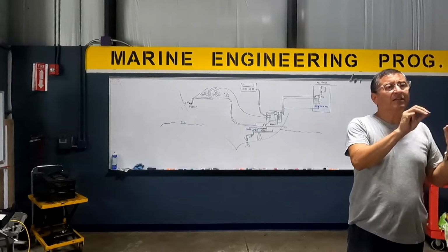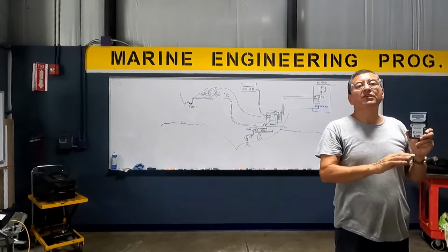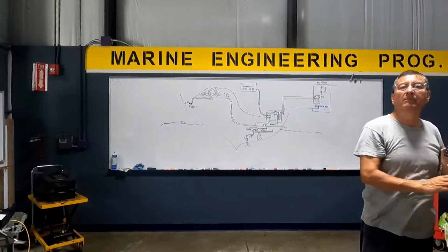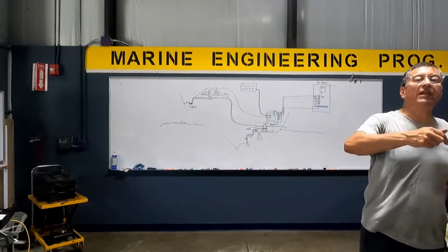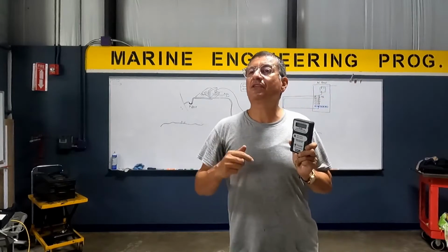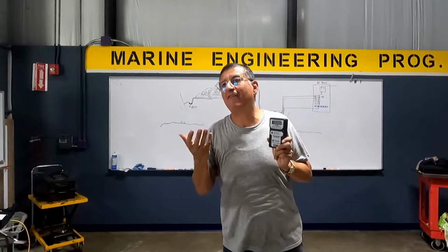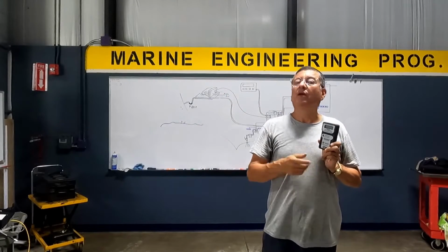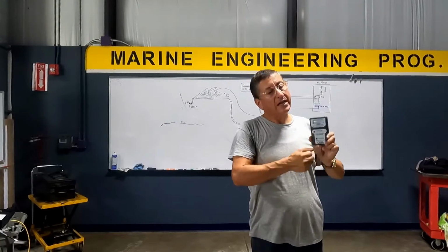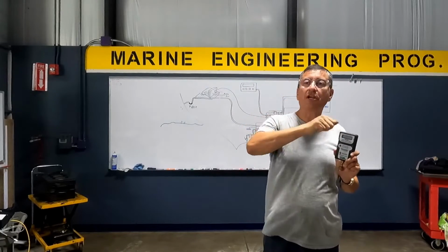When it's around 500, 400 microns, the system is considered with zero humidity. And in that moment, you stop the pump and you can recharge the refrigerant, new one, fresh refrigerant. I don't recommend recharging the system with the used refrigerant, because the used refrigerant has moisture, no? With fresh refrigerant, you recharge the system because you did the vacuum according to this, and now you are ready. In the video, I did the vacuum for one unit here, and I recharged the system.